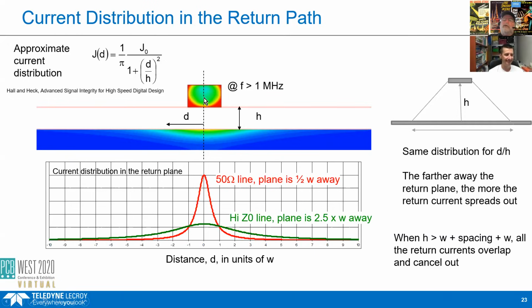This is long range. I mean, you don't have to have overlapping return current to have inductive crosstalk. This is going to give magnetic fields. Yeah, I understand what you mean. But if we get it really close, and you have to get really, really extremely close in order to have that extra crosstalk due to the overlap of the return currents. But if you pull them apart, you're still going to have crosstalk.